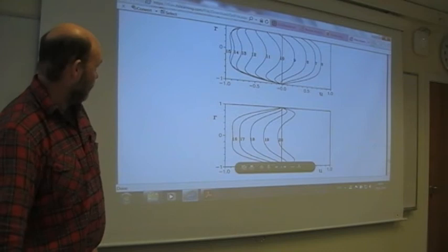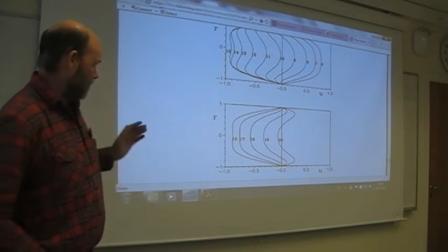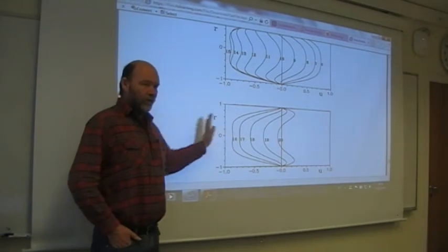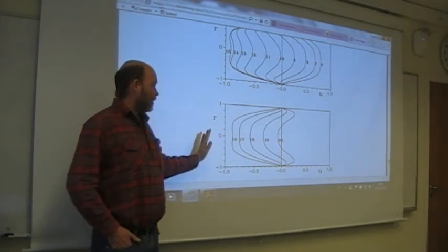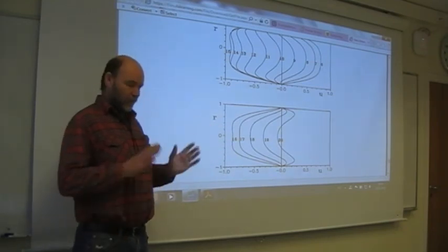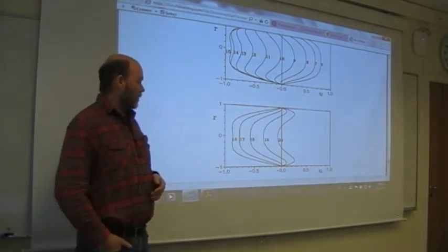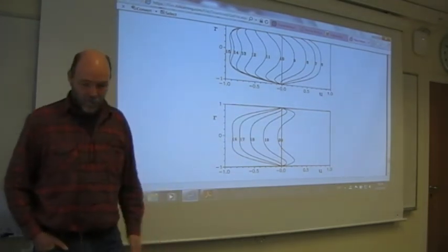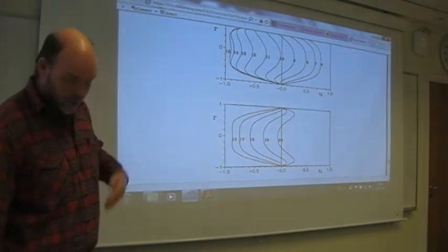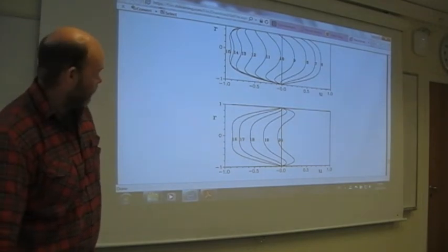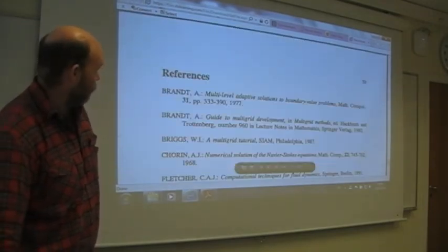So you get quite strange velocity profiles. I mean, you have two effects here. You have the size, the strength of the driving force, the pressure gradient, and then versus the frequency. I mean, if the frequency is too high, nothing is going to happen. The fluid just vibrates. If the frequency is too low, okay, then you have just a classical Poiseuille profile, developing first one side and then easily go back to the other side. So there are some parameters you can play around with here.